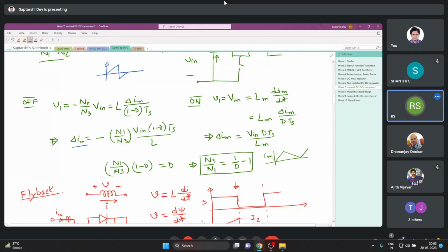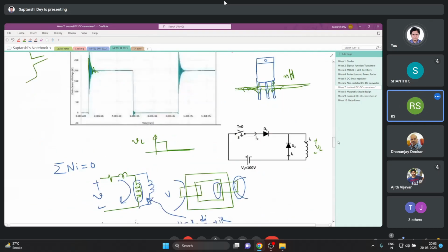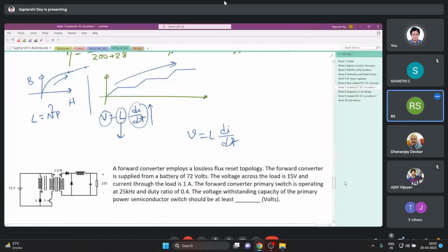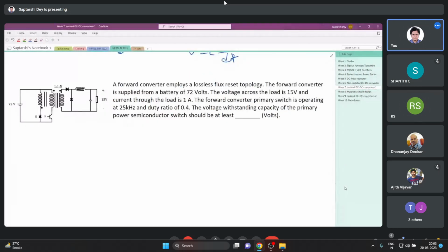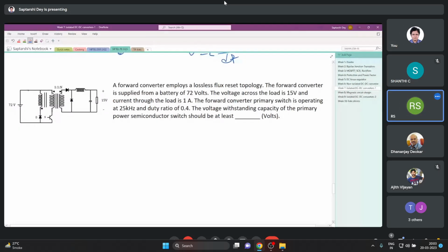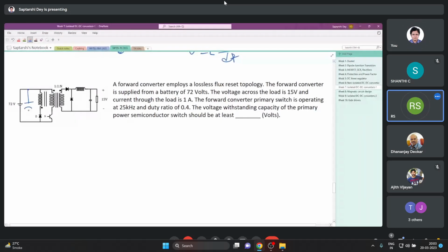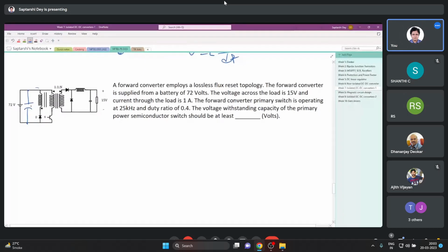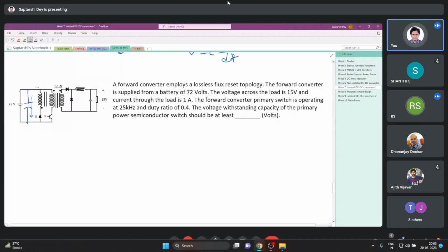Sir, in that case, there will be a momentary increase in the source voltage itself, right? Actually, such cases we handle with capacitors. The current that is going back will be absorbed by the capacitor, and when the switch is closed again, energy will come back. So the capacitor will experience a voltage ripple, which will be reflected as an increase or decrease of the source voltage.